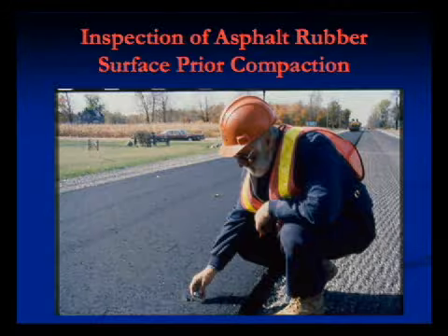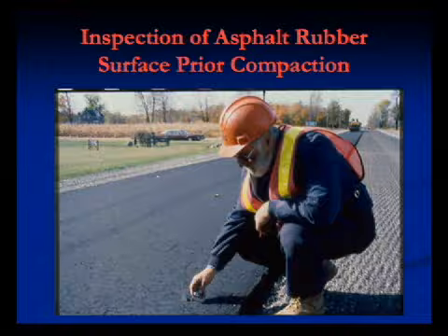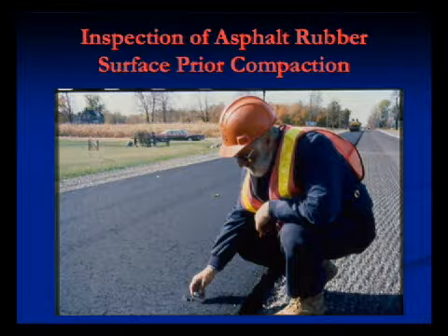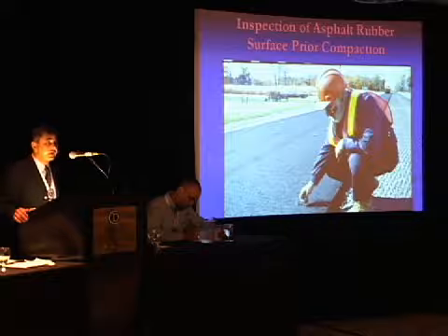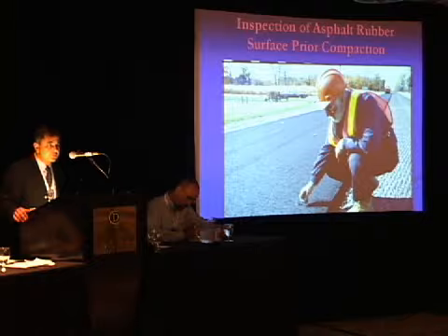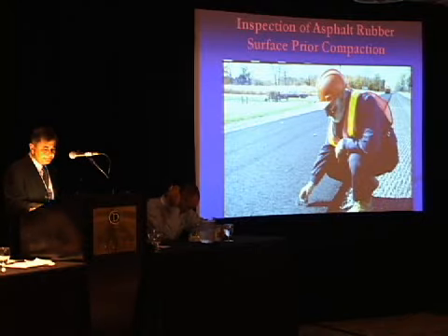This inspector is so focused on getting the asphalt rubber broken down and rolled down at a high temperature, but if you have problems out in the field, temperature could be one of the problems. Mix design could be another problem. Aggregate size could be a problem, but crumb rubber also does play a role in the performance of your asphalt pavement.